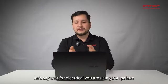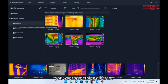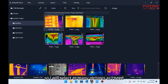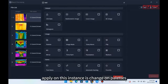pictures. Let's say that for electrical you're using iron palette, but for building inspection you want something different. So you see that some of these are with iron and some others are with a different palette. So I will select as many pictures as I need. Click on Tools, Batch Processing, and the task that I will apply on this instance is Change of Palettes.